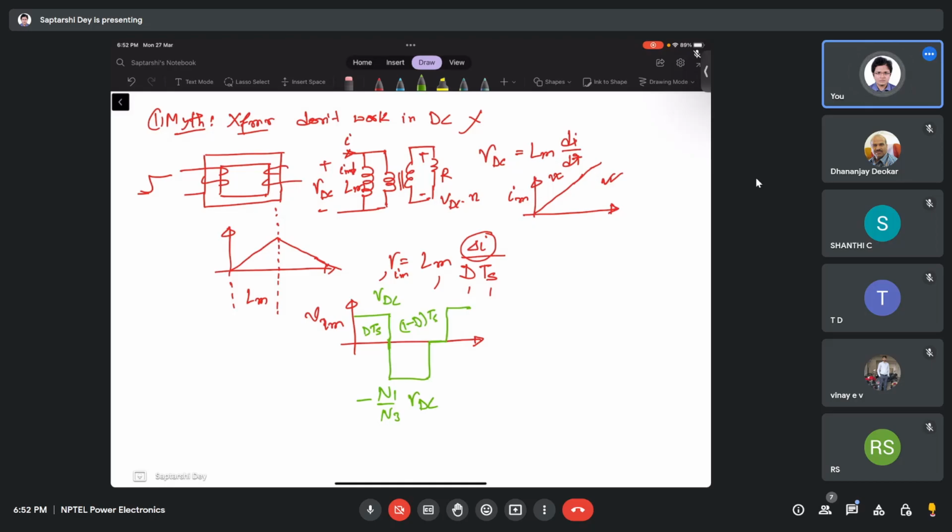So when you are making the statement that transformers don't work in DC, you always say at steady state. At transient they do, and if you have enough capability to supply that power and that much current, and if the windings can take that much current, it will keep working in DC, ideally speaking.